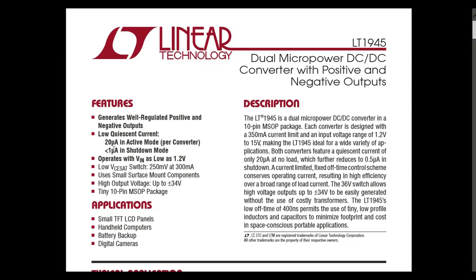It operates with a very low input voltage, V in as low as 1.2 volt. With an input close to 1.2 volt, it is going to boost up the output with a low V sat of 250 millivolt at 300 milliampere.